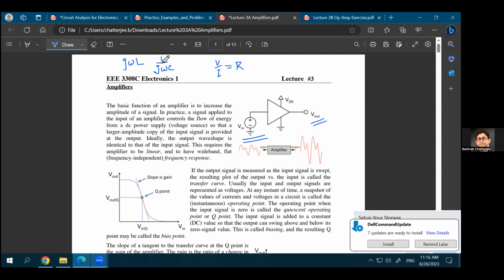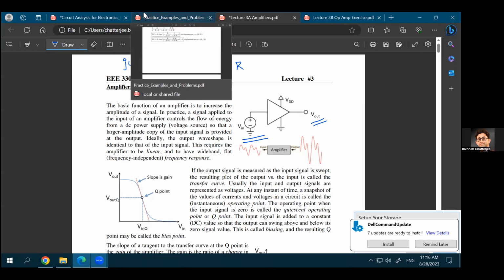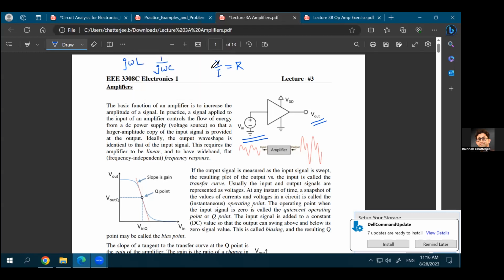Impedance means that you can have a physical resistor, capacitors or inductors, but the overall impedance, the overall voltage over current in that circuit, is given as impedance, which becomes a function of frequency because inductors and capacitors are a function of frequency. So impedance is a more generic term as compared to resistance. But in a more simplified form, they mean the same thing when you don't think about frequency at all.